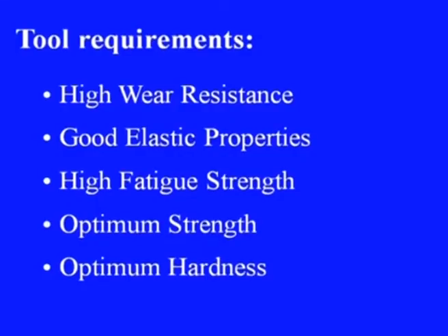Mass of the tool should be minimum possible so that it does not absorb the ultrasonic energy. Then what are the other requirements of the tool? It should have high wear resistance, should have good elastic properties, it should have high fatigue strength, as it will be continuously subjected to fatigue kind of loading under very high frequency.